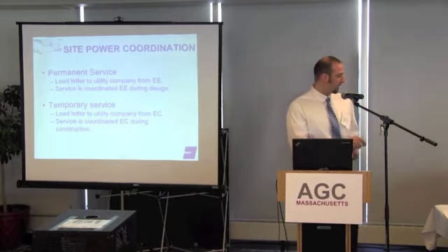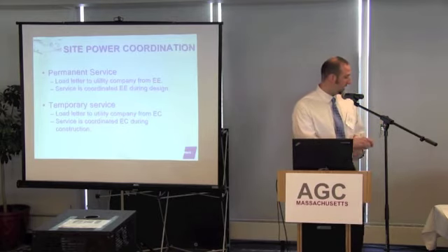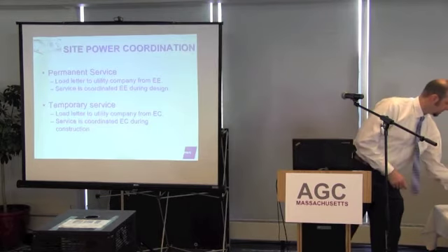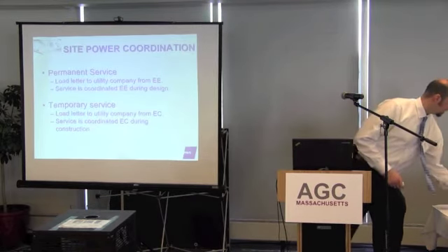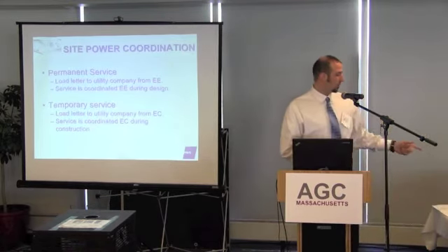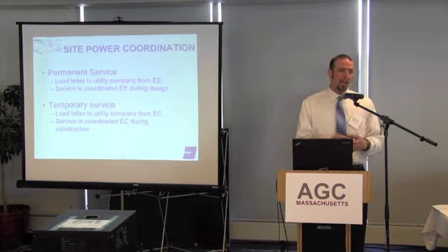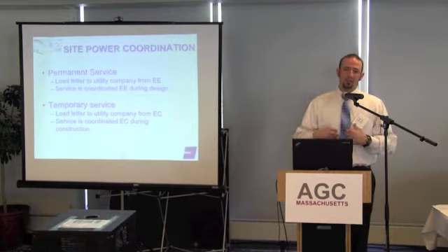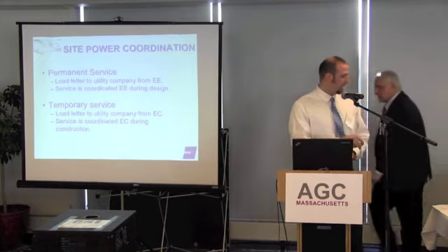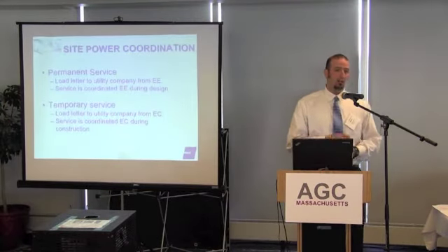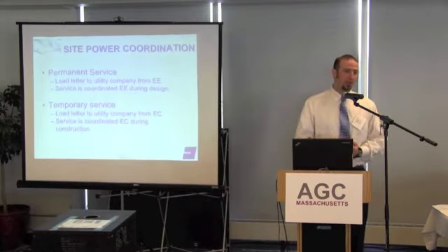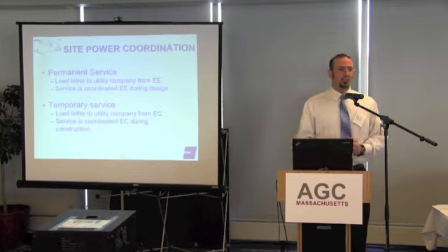So much like we size our service, the switchboard that you see in E201 has to be sized for the loads of the building. What we provide to the utility company is a site plan that you see in E002. We provide them a riser that you see in E201. And that tells them how the building will operate.